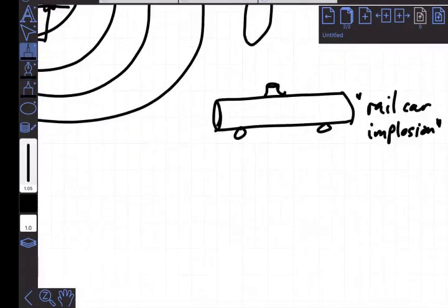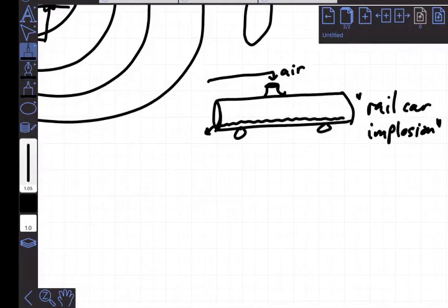And basically the problem that the vacuum breaker is supposed to alleviate is that, imagine that when you empty this vessel out, it's empty. But actually what it contains in many cases is either air, or if you forget to leave this entry port open, and you have a small amount of liquid lying at the bottom of that rail car, on a hot day, that can actually evaporate.